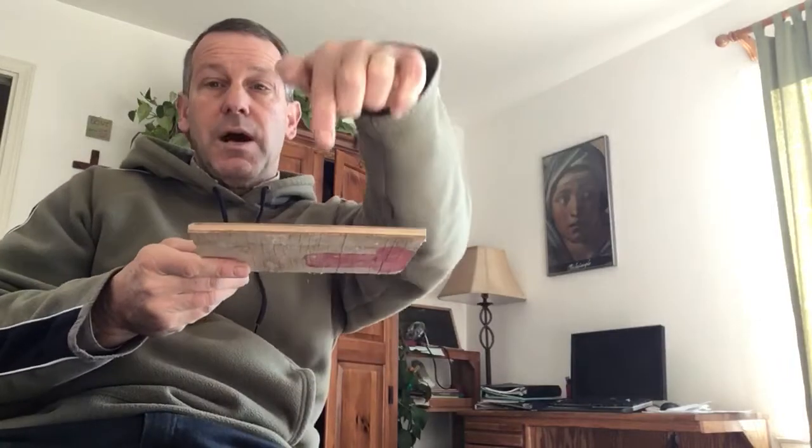All right, so easy enough to figure out the U. We talked about that last time. I'll review it really quickly. But what about the area? How big do we need to make this plate given that we want a certain amount of heat transfer? And the example I'm going to do, let's say we want 40,000 watts. We got this oil coming in and we want to get 40,000 watts out of it so it comes out at a cooler temperature. 40,000 watts heat transfer. What area do we need? Okay, and that's a really fundamental question that you might get involved in design if you're doing stuff with heat exchangers. All right, well, let's get at it.